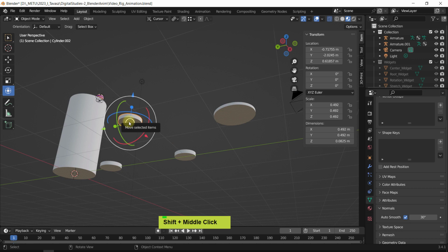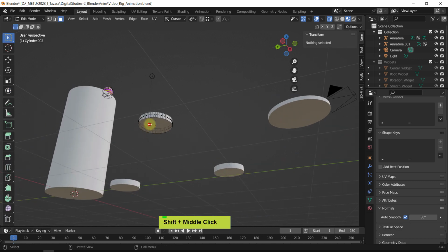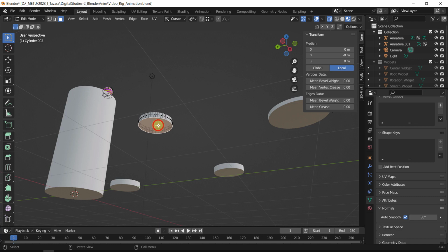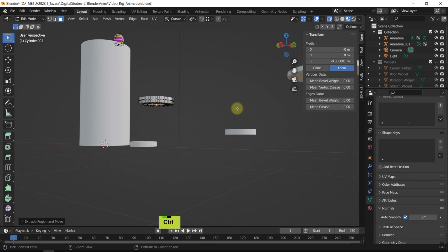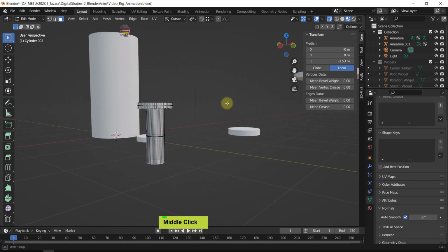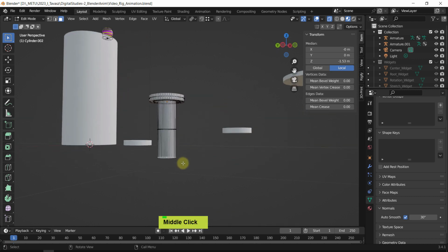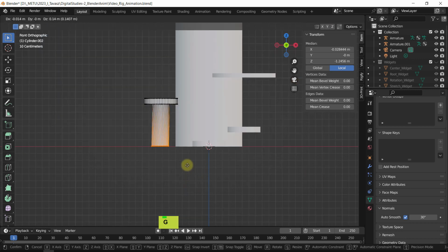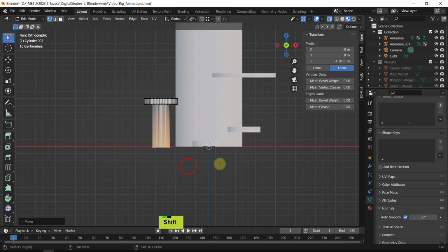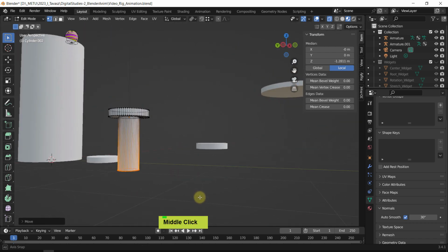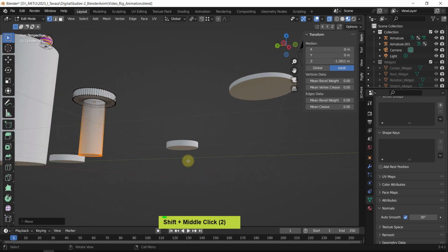And just to have a better glimpse on where we are, and to have a better sense of the whole 3D scene, I will go and select polygons at the bottom. So polygon, and click on this, and I as inset, and E as extrude, and that will be at 0. So I will set up, okay, we are going to global and select the vertices, for example, and going to the front viewport, and G, and on the z-axis, moving them up. Okay, so we will do something similar. This one's already on the ground, this one's already on the ground.